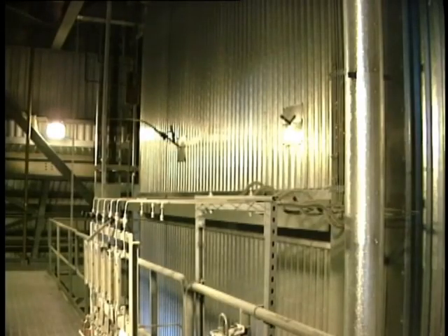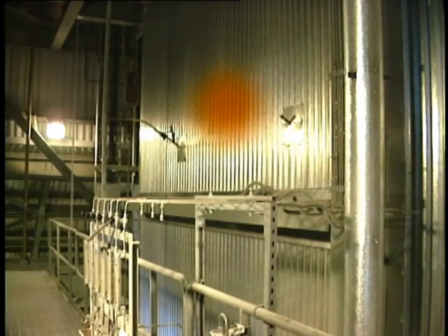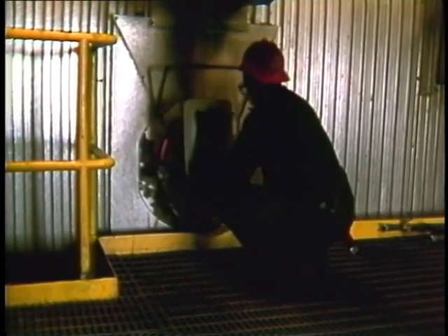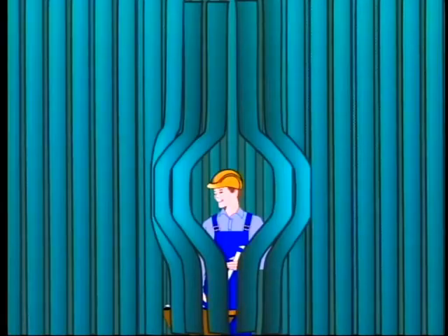However, where insulation is faulty, we will feel the high temperature in the locale, and the boiler casing may glow red. Access ports are often provided to allow us to look into the furnace at strategic points and also to enter the furnace during maintenance shutdown. At each of these locations, the water wall tubes are curved around the entrance hole to allow access.